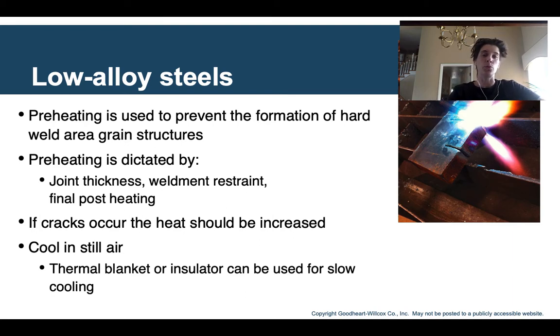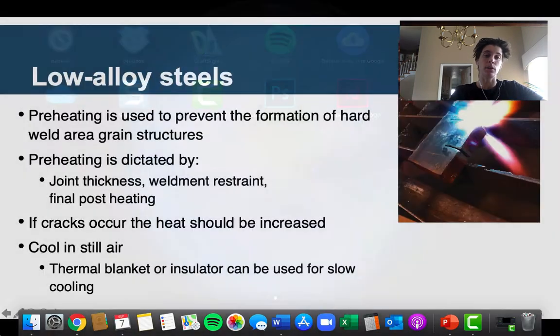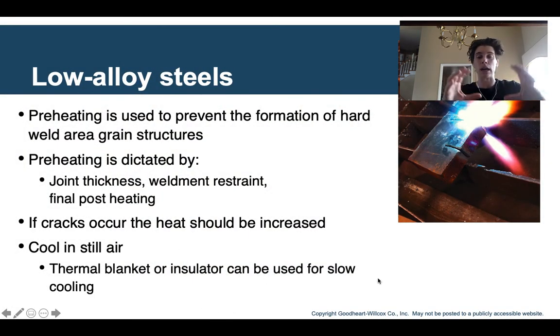Generally, you cool the weld in still air, meaning like not in front of a fan. You don't want to quench it in water. That defeats the whole purpose. Sometimes you would even use a thermal blanket or another insulator to slow down that cooling. Usually slower cooling is better for this procedure.